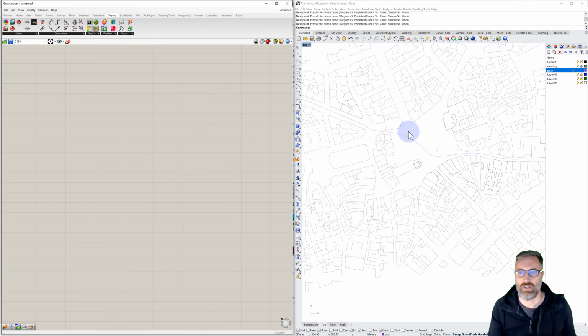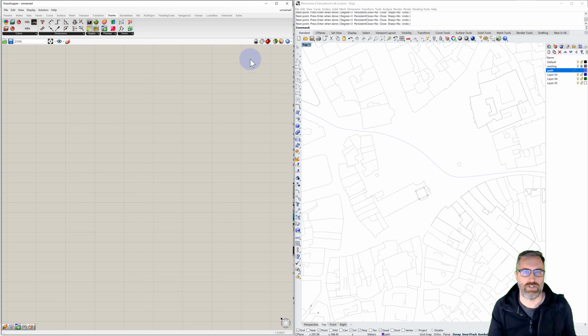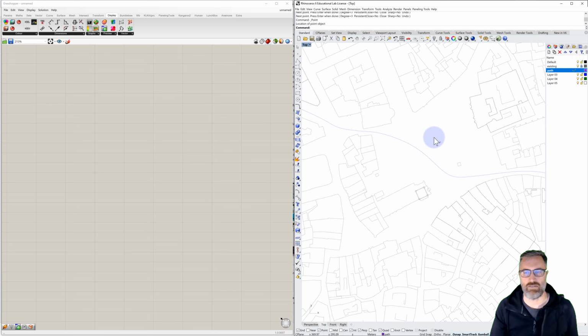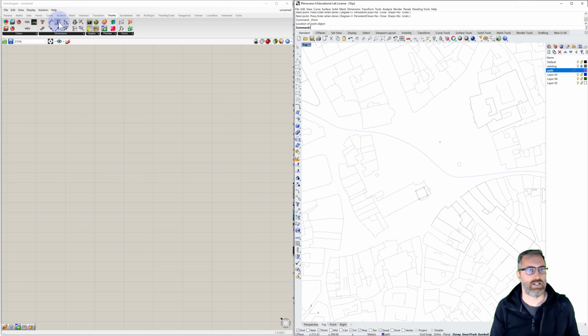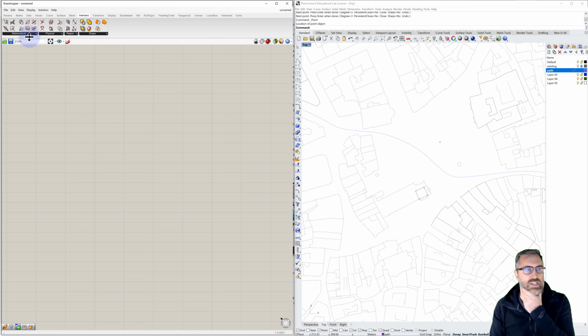So let's do a couple of things. Maybe let's start with just a point. As a way to introduce the key tool that we'll be using, now we have a point in the main space. We're going to use a tool called Isovist. And I think I mentioned this at the beginning. The Isovist is basically going to set a series of lines radiating out from a point in space, and that will go until it reaches an obstruction. And so Isovist is under Intersect and under Mathematical. We can see Isovist and Isovist Ray. So let's pull down Isovist and see what it's looking for and what we get here.